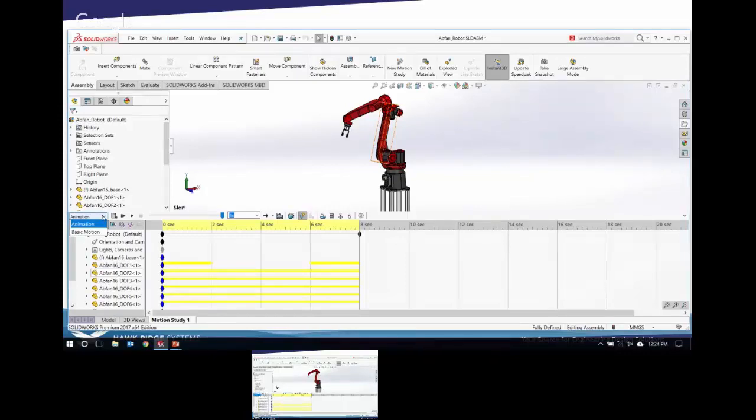When you do that, do you pull a license of Premium because it's using SIM, right? Well, not for the basic motion, but for motion analysis. Basic motion is free for everybody. Yeah, but that's what I've done: always put that on basic motion instead of the animation. You have better results.